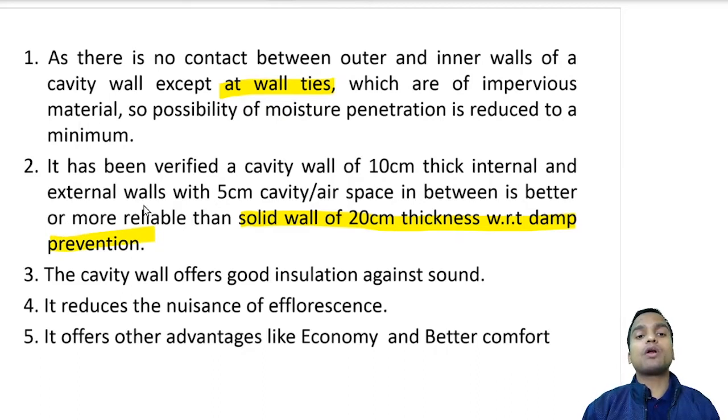Now the cavity wall offers good insulation against sound also. So this is an additional benefit of the cavity wall. If you want a room, a theater or an auditorium which should be soundproof, meaning no external sound or noise should disturb the interior environment, then a cavity wall is very important. Now it also reduces the nuisance of efflorescence, and it offers other advantages like economy and better comfort.